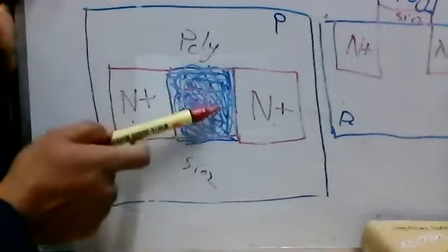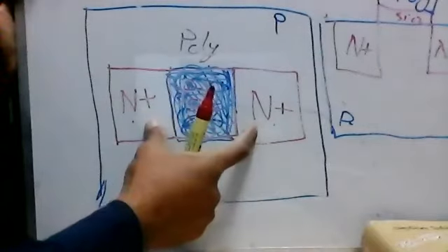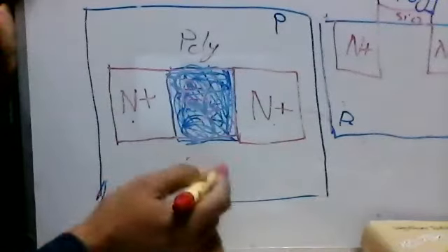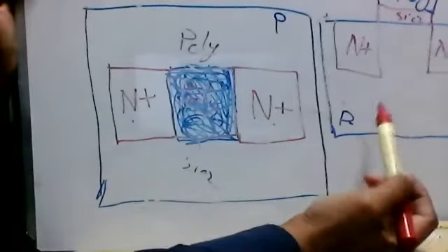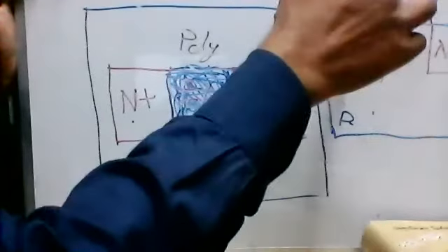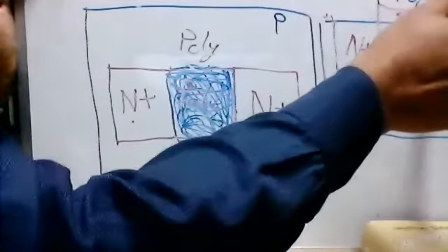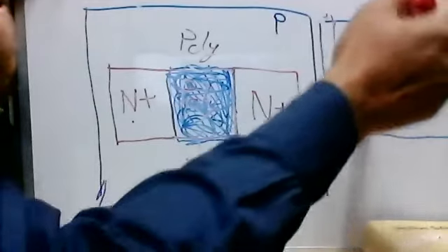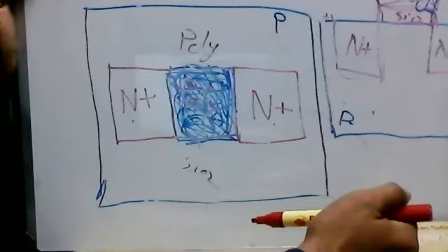material. Now you look at that: the first layer is the P-type substrate, the second layer is the N plus N plus, and the third layer is the silicon dioxide, right? We put a silicon dioxide, and the fourth layer is a polysilicon. Now in here also, you can see that this is the first layer, P-type substrate, and then we inject those N-type materials here and here, and then the second layer, and then the third layer is a silicon dioxide here, and the fourth layer is a polysilicon. So there are a total of four layers.